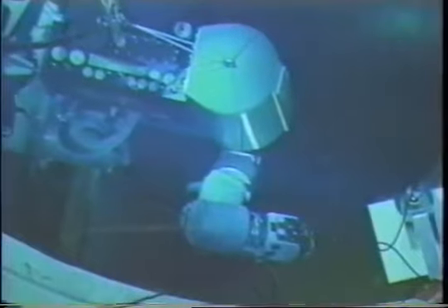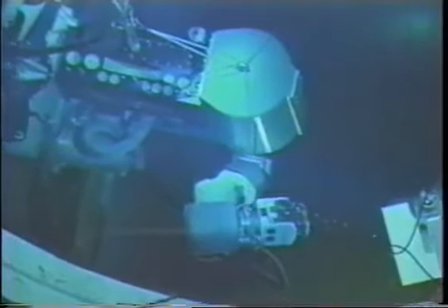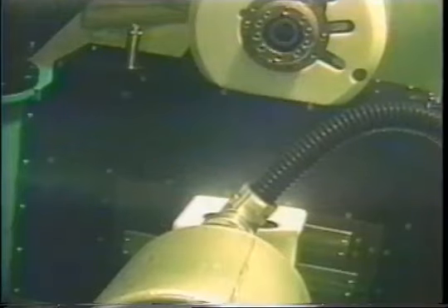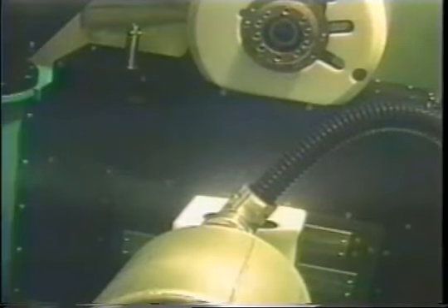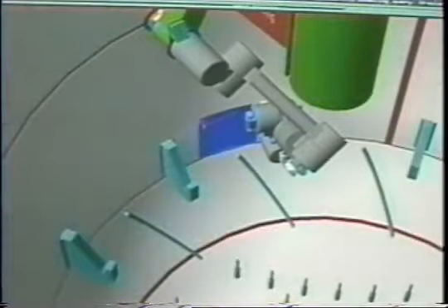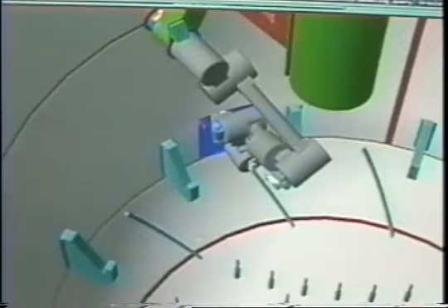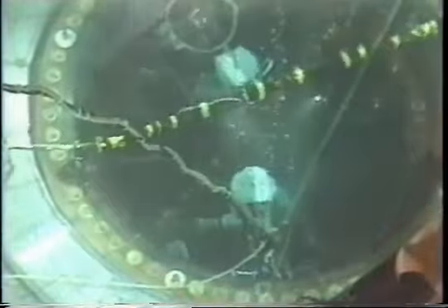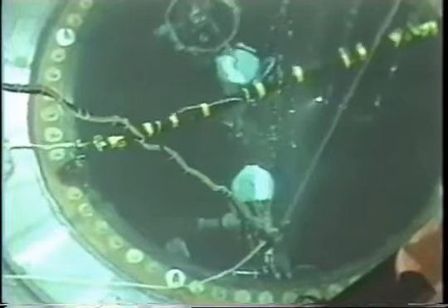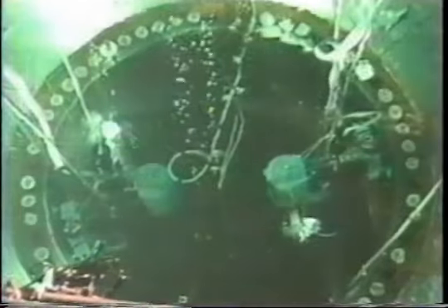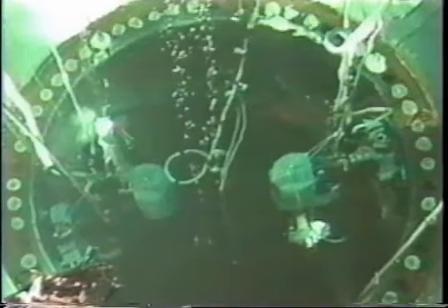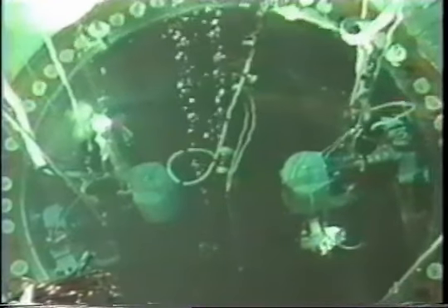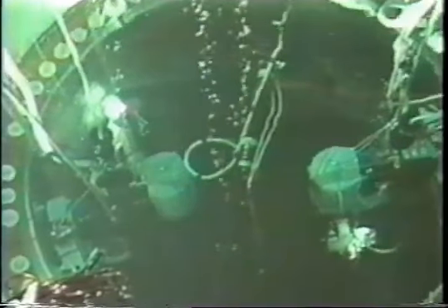The IEEE code requires periodic calibration checks. Ursula's onboard calibration blocks permit UT calibration checks with minimal interruption of vessel scanning. Ursula's compact design enables 2 robots to simultaneously scan and examine the reactor vessel in approximately 60% of the time required by 1 robot. 2 robots also ensure completion of the examination on or close to the target schedule.